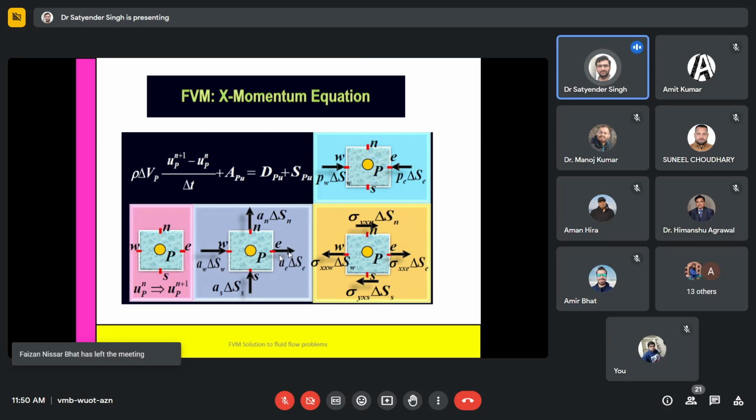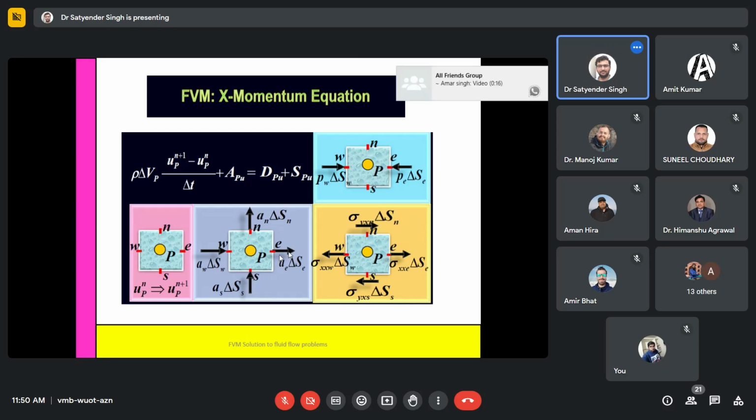But you must remember that when we derive this advection term, the overall material derivative, or Eulerian form, has been represented by taking a variable which is a function of x, y, and time. So by applying a Taylor series or a chain rule, that gives you the unsteady term plus the advection term. I think you will be well familiar with all this derivation.